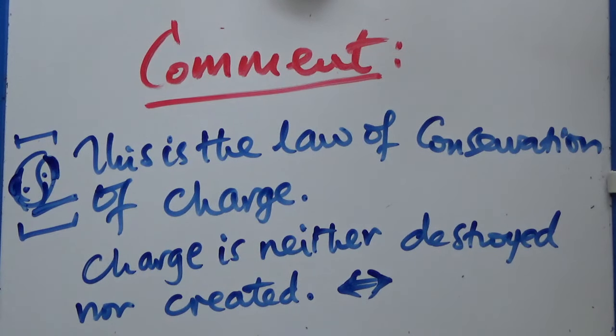So that is Kirchhoff's current law. Some people will say law 1, the other one will be law 2, but let's make it more specific. Kirchhoff's current law. We stated it that the algebraic sum of the currents entering a node or branch point is equal to the algebraic sum of the currents leaving the node or branch point.